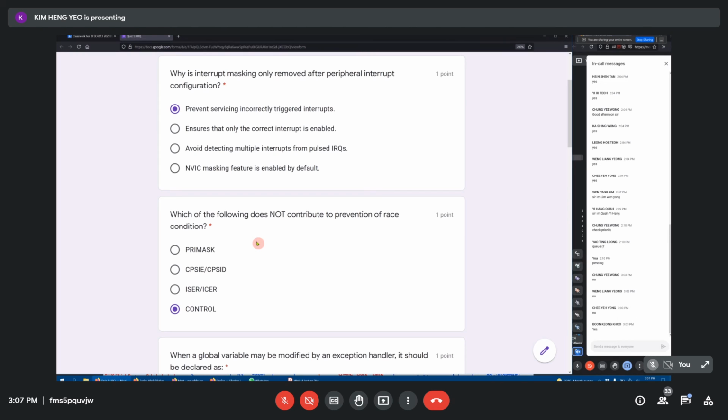While I'm changing the value of these 4 integers, an interrupt happens, and then the interrupt goes and changes the value of one of the variables. After that, the interrupt is done and returns back to me. I didn't know that the interrupt did something, so I continue. So what happened now is the value that I'm modifying has been corrupted by the interrupt service routine, and I don't know, because I didn't know the interrupt has happened. It's just like a ghost, going and moving the ball.